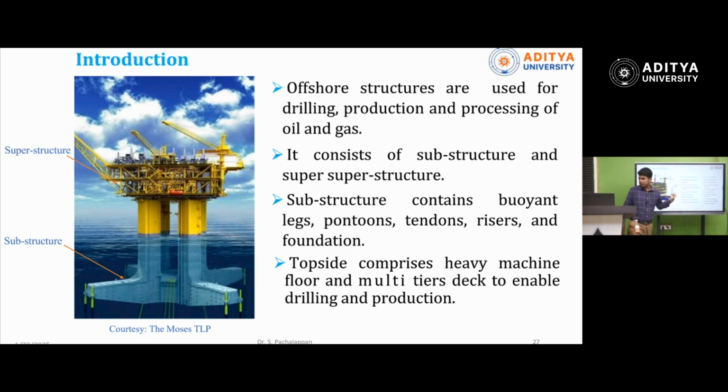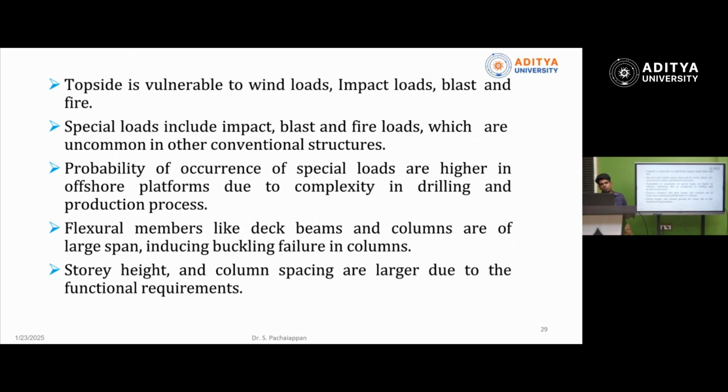This offshore structure is highly vulnerable to hydrocarbon fire, explosion, impact load, wave load, wind load, and fire. That is the reason these structures are complex and we need to analyze them properly by using the proper material and design. So as I said, the topside is vulnerable to special loads. Generally, the word we use, special load, includes